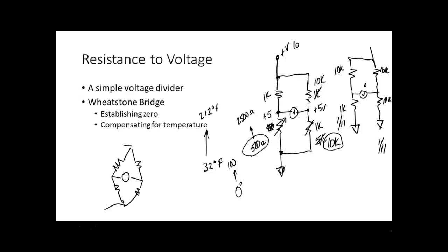So load cells use something called a strain gauge that varies its resistance with weight. And a load cell includes the Wheatstone bridge in the cell itself. And so what we do out of that is we get a voltage out of that that represents what? That represents weight.